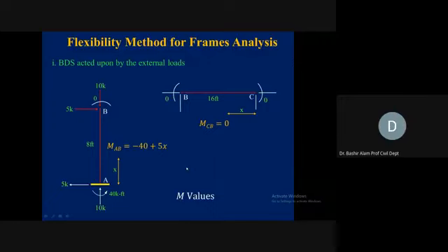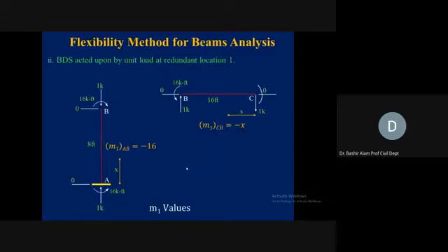We go now to M1 values corresponding to C now. Here, if you remember, AR1 was in the vertical and it was in the downward direction. So at the same location in the downward direction, we are applying 1 kip. Summation of Fy is 0. So at B, the reaction is becoming 1 kip in the upward direction.